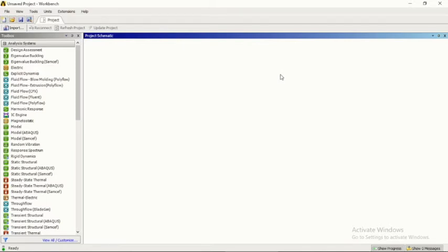Now we will see how we are going to model using the Design Modeler. In this approach, I am going to model two line elements, and then with three nodes and two elements, I'm going to transfer that model into the mesh and the model generator, and then I will solve that using ANSYS.